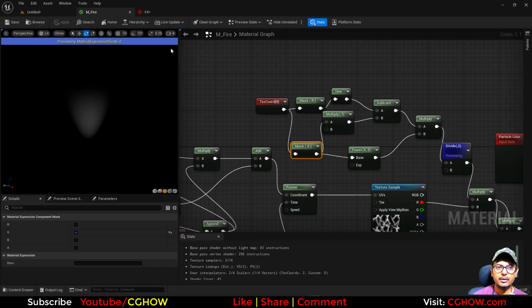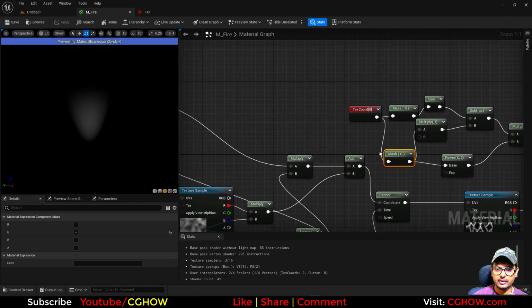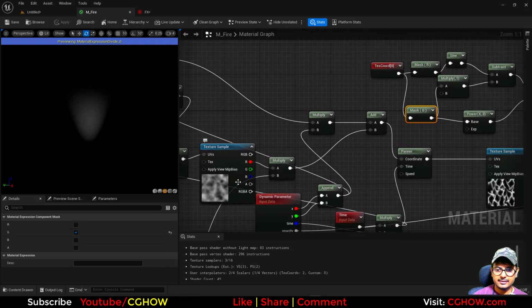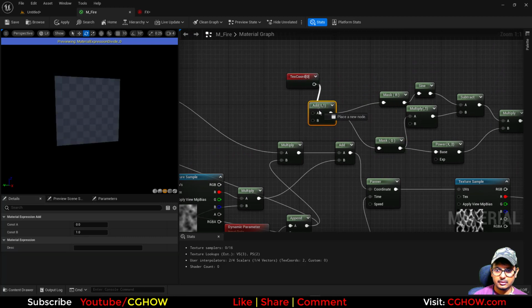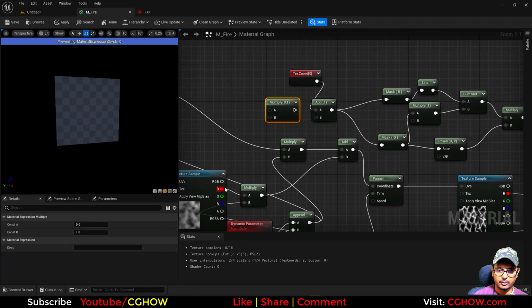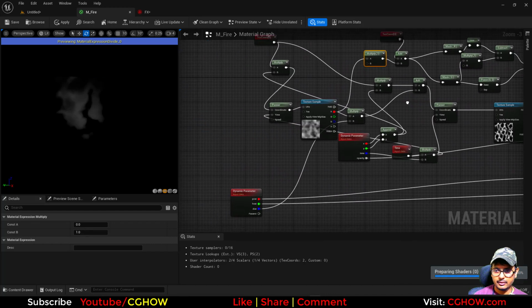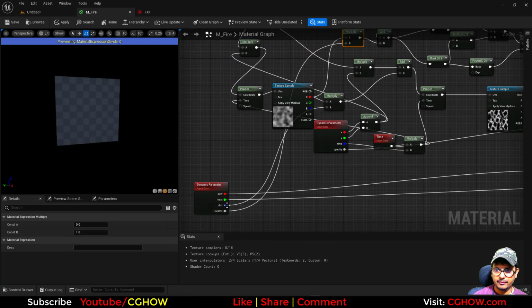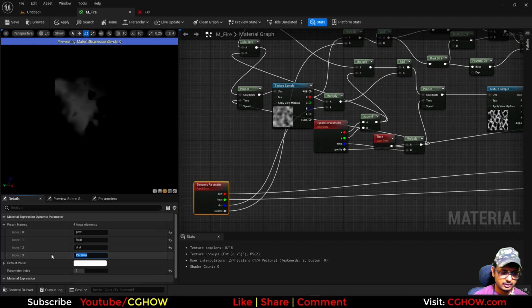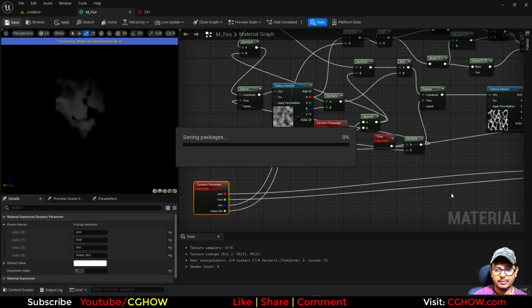And you can do one more thing. Your shape is a very proper V shape. So you can use that same noise to distort it. So if I add that noise here also, and then in this dynamic parameter, we have a parameter for the shape distort. That V shape we can distort a little bit, not much.